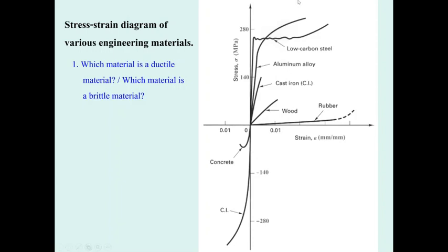You can see that the strength of a material can be defined by the yielding stress of the low carbon steel. That is going to be about 250 or 260 megapascals. This material has a clear yielding portion, so you can find the yielding easily. However, for the aluminum, we cannot find the yielding region, so we have to use the 0.2% offset. 0.2% is 0.002.